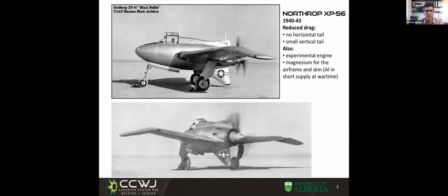This rod is made out of tungsten because tungsten has two important properties. One is that it has a very high melting temperature, so it's not going to melt. And two, for whatever reason, it is what is called a thermionic material. That is unrelated to the high melting temperature, but it's very convenient. What it means is it can lose electrons very easily in certain circumstances, which we will discuss later. But now we have a material that can take the heat and can give me electrons to start the electric circuit of having the electrons going through the gas.